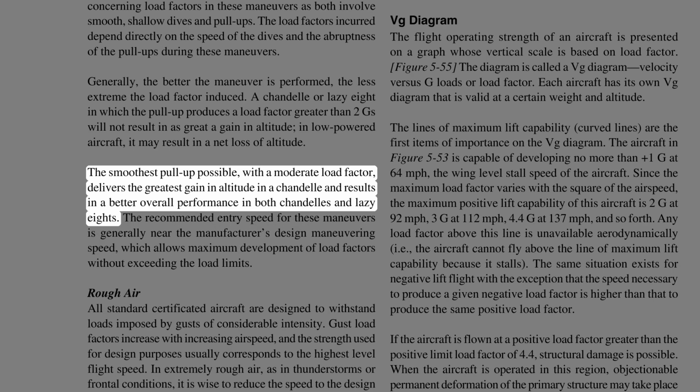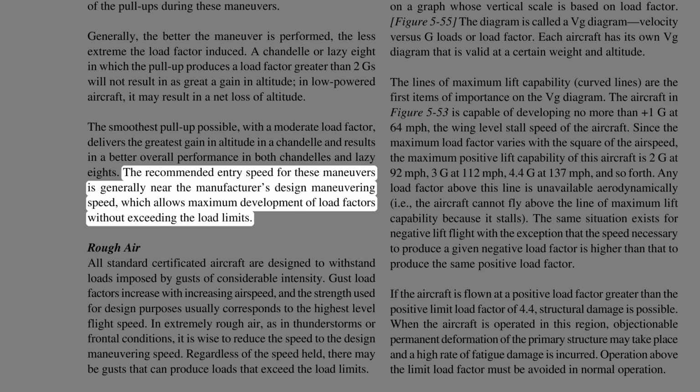The smoothest pull-up possible, with a moderate load factor, delivers the greatest gain in altitude in a chandelle and results in a better overall performance in both chandelles and lazy eights. The recommended entry speed for these maneuvers is generally near the manufacturer's design maneuvering speed, which allows maximum development of load factors without exceeding the load limits.